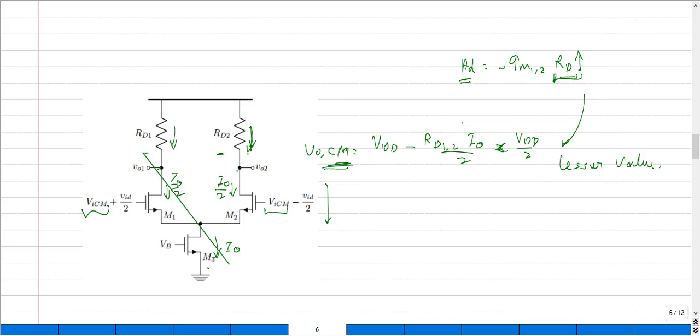Which is nothing but a simple PMOS structure. So this circuit has an incremental resistance when we look through the drain whose value is equal to R0. So this value is pretty large. But what is the voltage drop that is required across these two nodes? That could be controlled basically through the value of VGS, and what is required across the drain and source is basically our VOV, right? So in this case, the value of the resistance is so high and the drop across the resistance is so less.